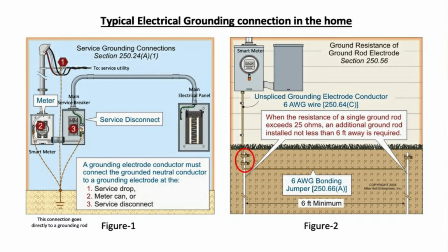But what's really important here too, as you can see in all these 3 conditions, is that the ground rod connection is making a connection into that neutral conductor again. We talked about this before: anytime we talk about this neutral conductor in the electrical engineering world, we have to think that this thing is always grounded somewhere. And in most cases, it's done in multiple places. So this is depicting that. And it's very important to see that, because this is going to tie into where I'm going to leave off on this video,